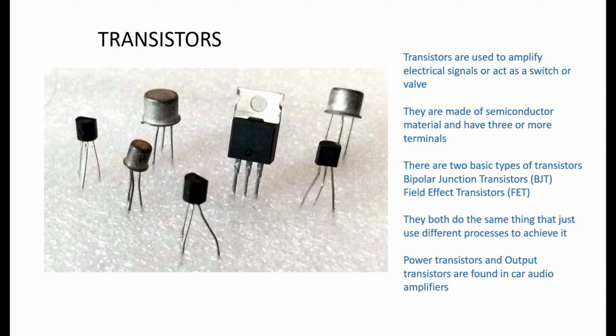an electronic component. In our car audio amplifiers, the power section has a set of power transistors, which we often refer to as MOSFETs, which are used to drive the transformer in the amplifier to supply power to the power rails. And the other important set of transistors found in your car audio amplifier is the output transistors. These are the transistors that drive your speakers and add the amperage that the speakers need to move back and forth.